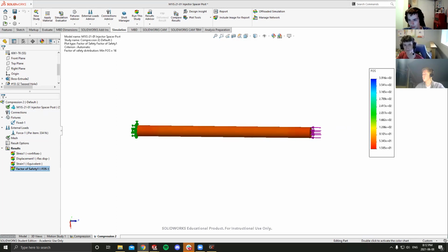For static or short-term loads, an okay safety factor is 1 to 2.5. For static long-term loads, 2 to 5. Repeated loads, 5 to 15. Variable changing loads, fatigue loads, impact loads are all there on that table.